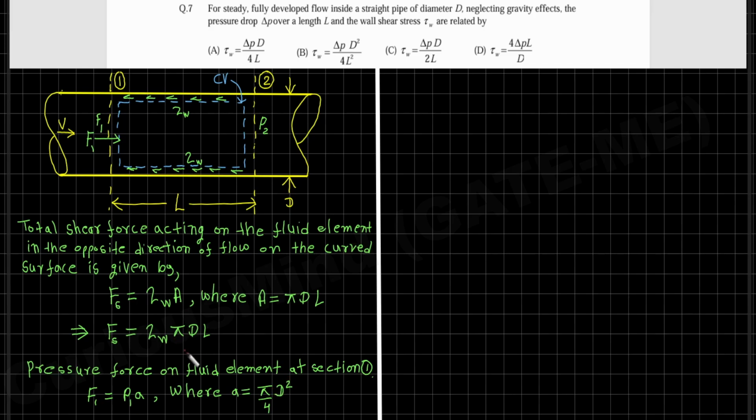Therefore, a force due to a fluid pressure on a plane surface is equal to the pressure times the surface area of that plane surface on which the fluid pressure acts perpendicularly. And the direction of that force becomes equal to the resultant of these pressure forces on the plane surface, which, in case of a plane surface, would be the same as the direction of the pressure.